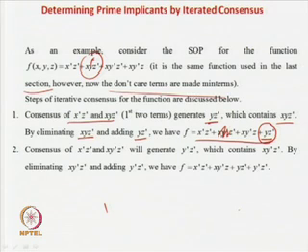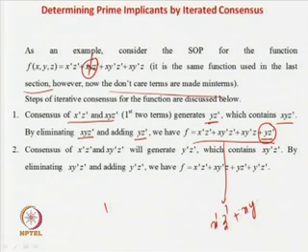Now, this is our new expression. Okay. So, now in the new expression, x y z prime is eliminated and this will remain; x y prime z prime is not included in this one. So, this is a new expression. In case this was x prime z prime plus x y z prime plus this stuff, you can now see that x y z prime is included in the last term, which is added. So, you remove this one, and finally you get x prime z prime, x y prime z prime, and this is the new term added.